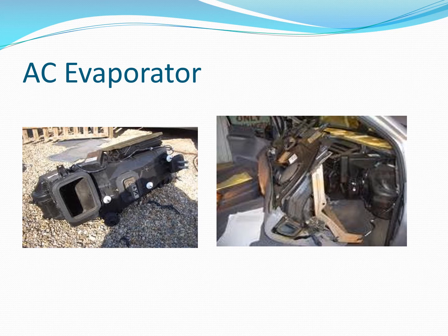If that looks like a pain to replace, you are correct. Most heater core or evaporator core replacements require dashboard removal to get to them. This is going to involve lots of small plastic parts and lots of screws removed. You need to make sure that you're keeping track of where all these items go as you're disassembling, because you're going to have to put it back. Also, you're dealing with lots of plastic parts that might break, so be cautious in removing this dash assembly as you are headed for the evaporator heater core box.